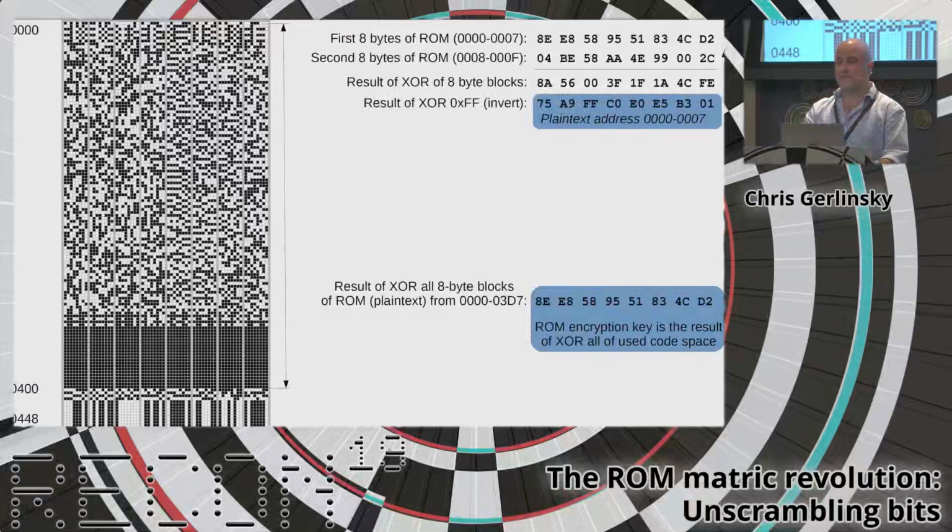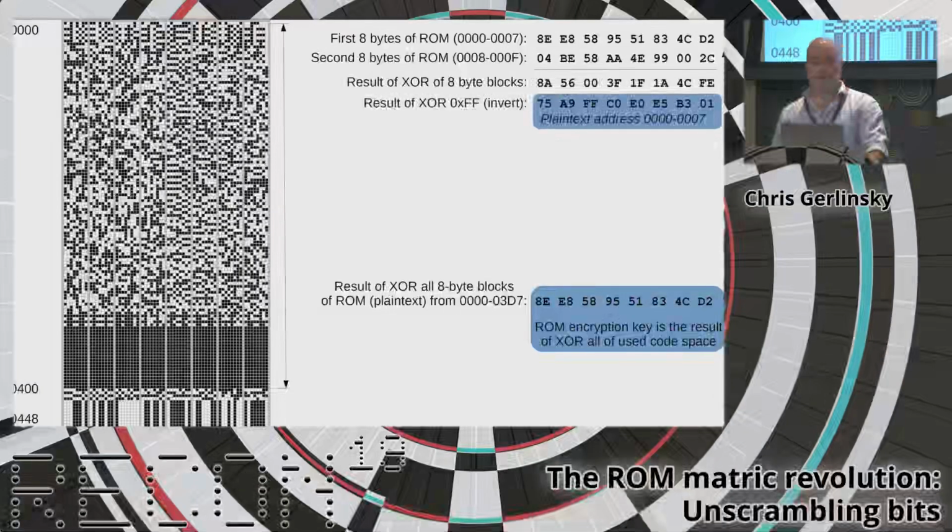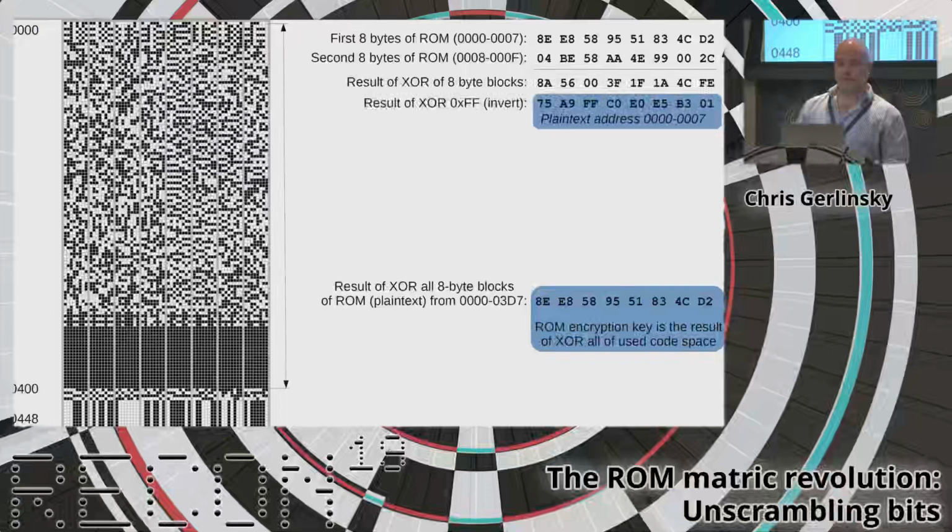And then as a side effect of that, when you encrypt to the end of code space, it ends up encrypting back to 0 at the end. So I don't know if they've done this intentionally, if it's just a way to try and hide the pattern of the XOR, because with a large area where you have all those FF bytes and you have a static XOR applied, then you start to see a pattern from that. But yeah, they had this weird little side effect where your empty space, in this case, ended up being not encrypted, but that actually worked to give some clues for how to decrypt it.